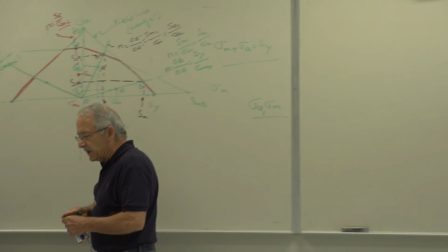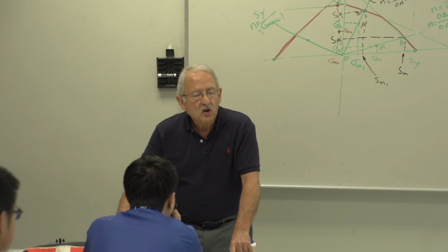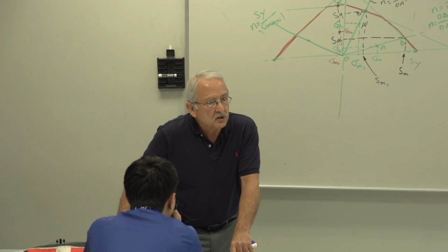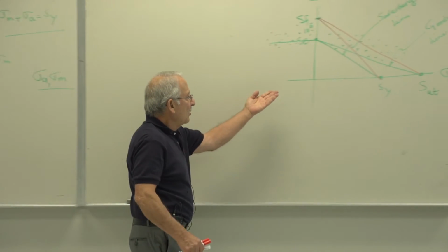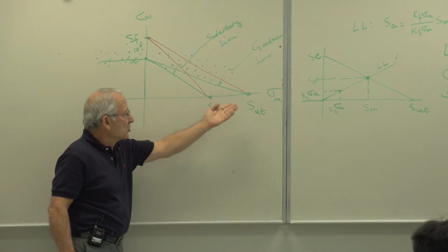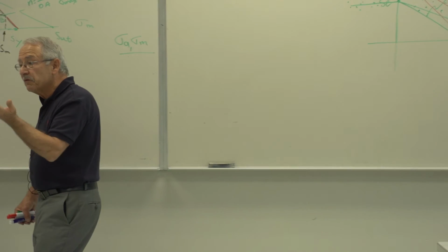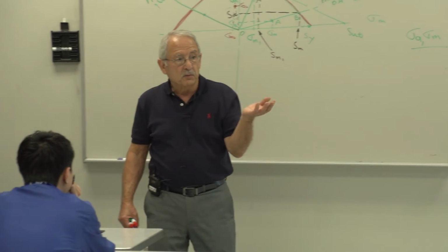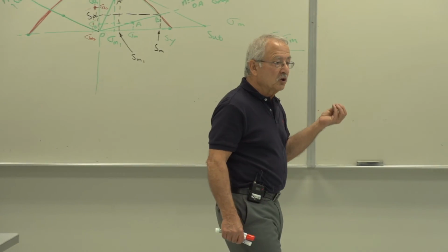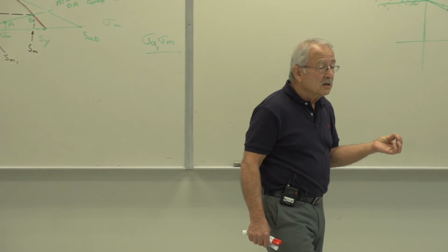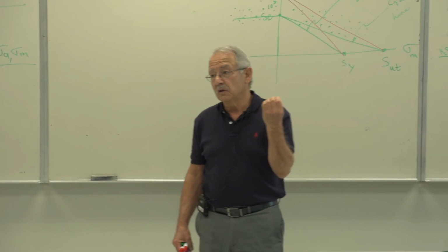We see that if the torsional mean stress, what we would be plotting on this axis if this were torsion, the torsional mean stress has no effect on the endurance limit of the material, provided the material is ductile, polished, and notch-free.